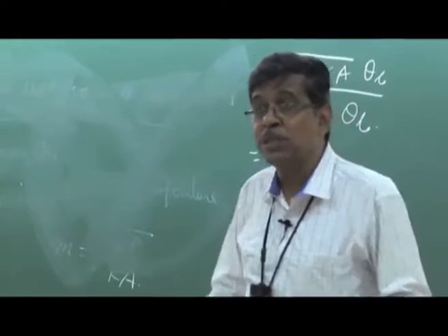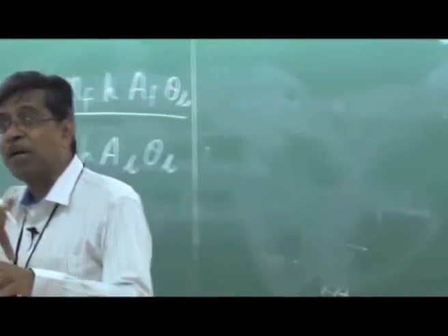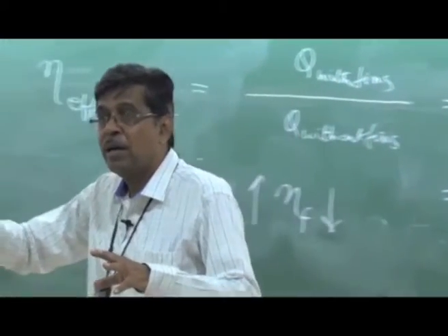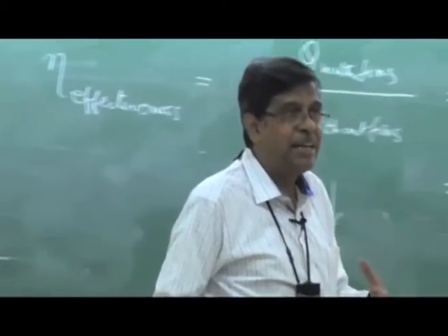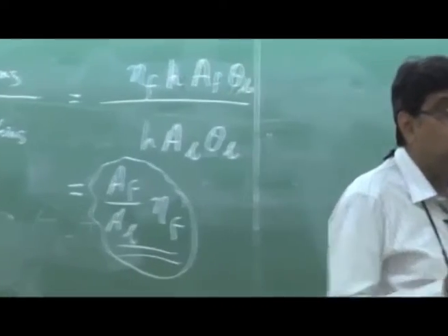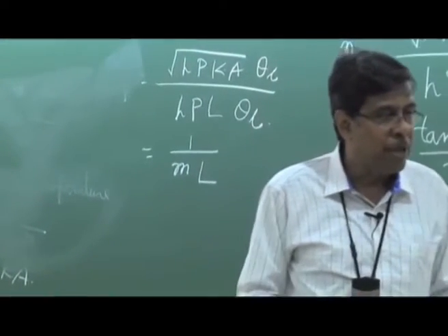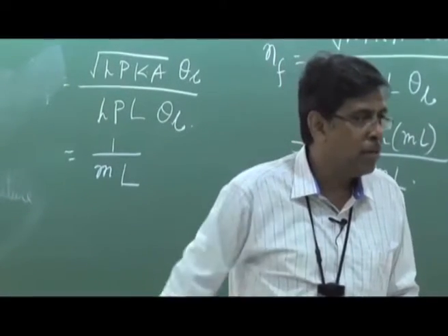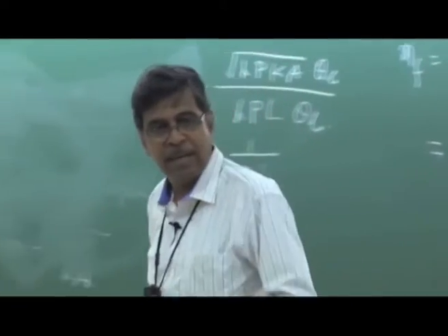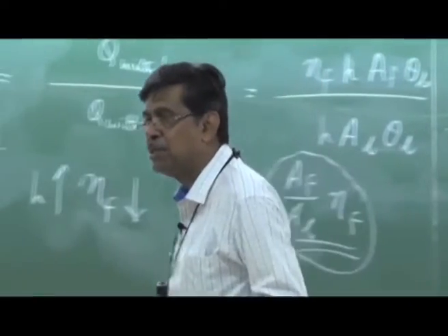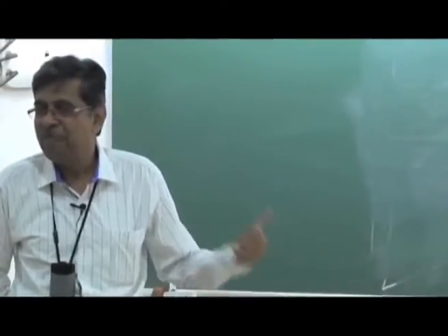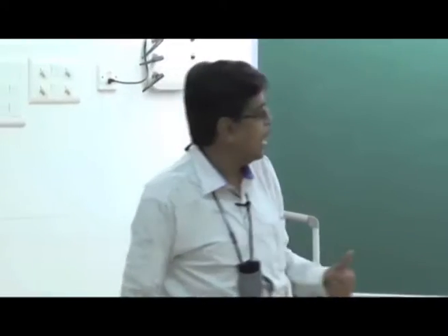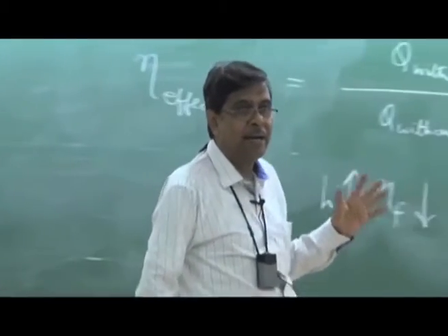So therefore, sometimes this question is asked: if you have a heat exchanger, on one side liquid is going and turbulators are there to create more turbulence in the flow field, and on another side gas is moving with a low velocity, which side will you provide fin? If you tell, sir, on the gas side, you get full marks. But if you say, sir, on the liquid side, flowing with high turbulence, get out. 0. Because this is the concept, that effectiveness of the fin. That means fin should not be used where the heat transfer coefficient is high. This is because of this fact. Okay? Clear?